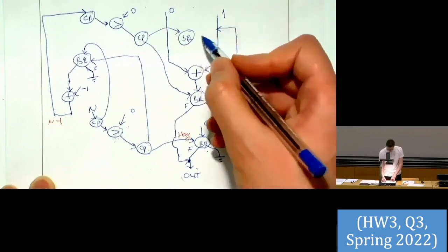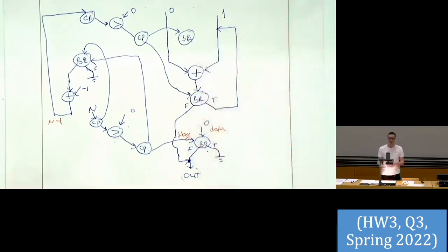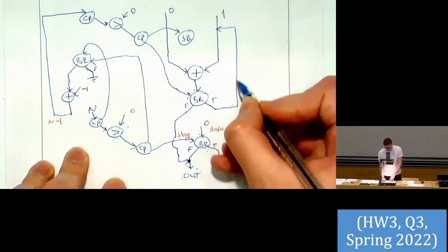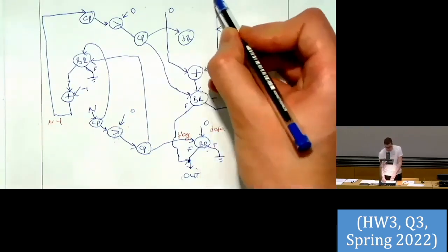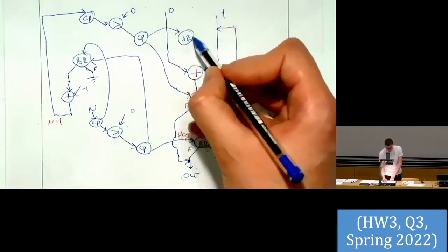But we'll need to forward the same value to this branch logic 2, because this will be the n minus 2, if you will, right? So this data forwarded here is just the result of the previous iteration, n minus 1, but we will also need n minus 2, right? And then we will get it from here.